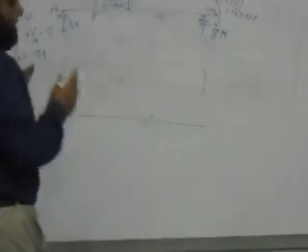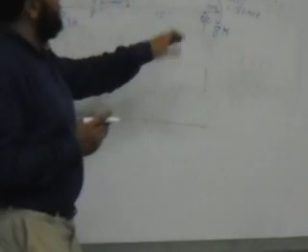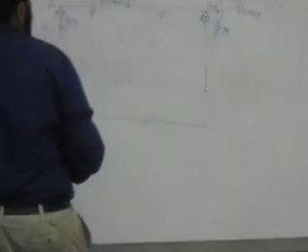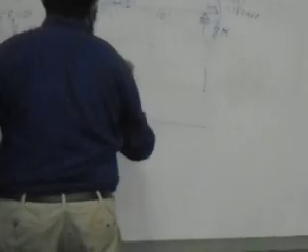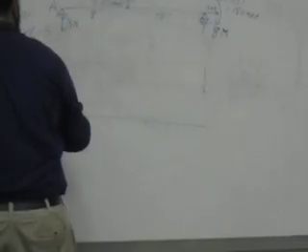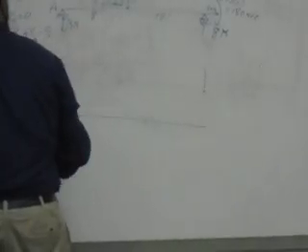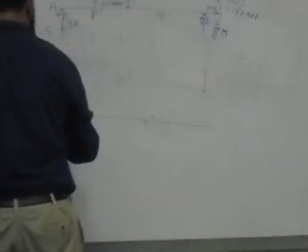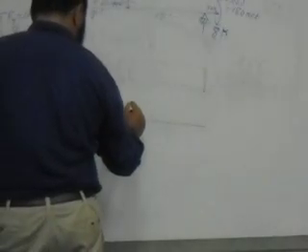Here we said this is the exceptional case. You need to take a section before B and after B, and before C and after C. So before B, what does it come out to? Just before B, it will be 8 times the 3. Is it positive or negative? Negative. This is negative 24. So here it's negative 24.